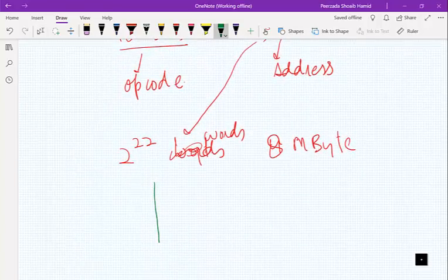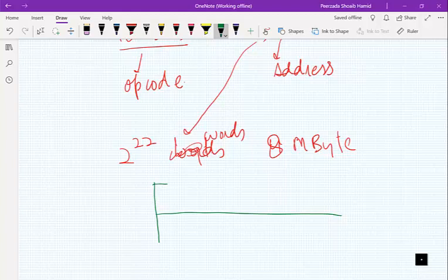So we have something like this. LEDs are turning on and off by high and low. We have a square wave at the pins of port B. T on is 0.2 microseconds and T off is 0.2 microseconds. The point here is, can we visualize this? An LED is blinking with a time period of 0.4 microseconds.